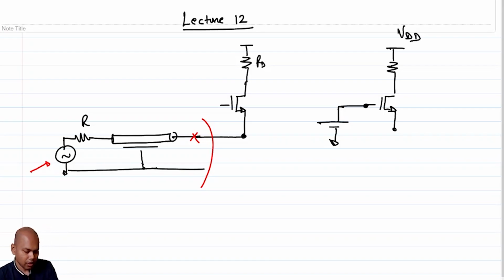Now one might say that a zero quiescent point is good, because if the gate of the transistor is biased with a VG and the source has a zero quiescent point, that probably is the best case scenario, because I can have a sufficient amount of VGS to keep the device turned on, and I can also provide the incremental inputs.